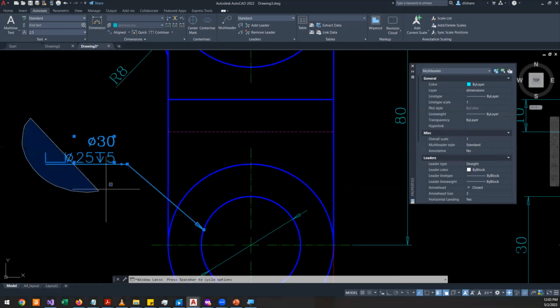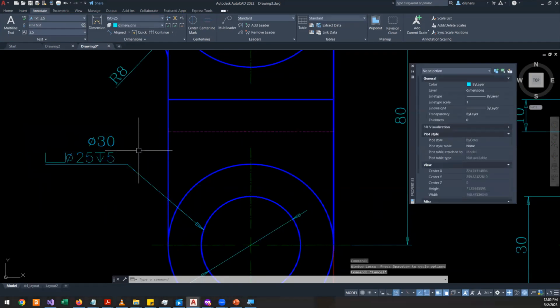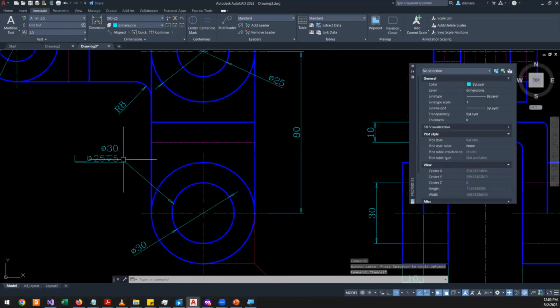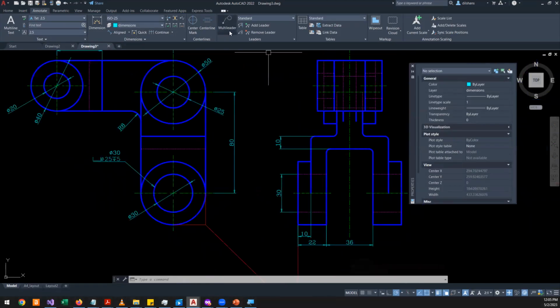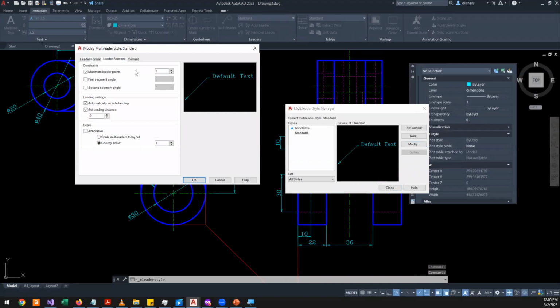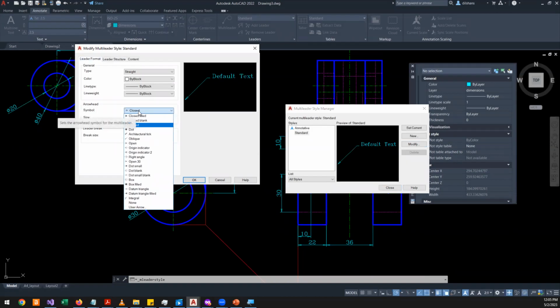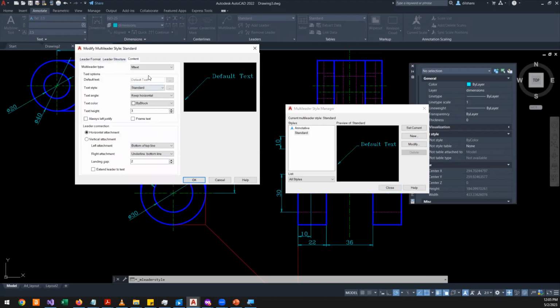Yeah, again, this information is wrong. I just wanted to show you how to add this kind of information into your drawing. So for that, I used multi-leaders and formatted it. You need to be consistent. That's what I want to highlight. You need to be consistent with the arrows and the text height and the font.